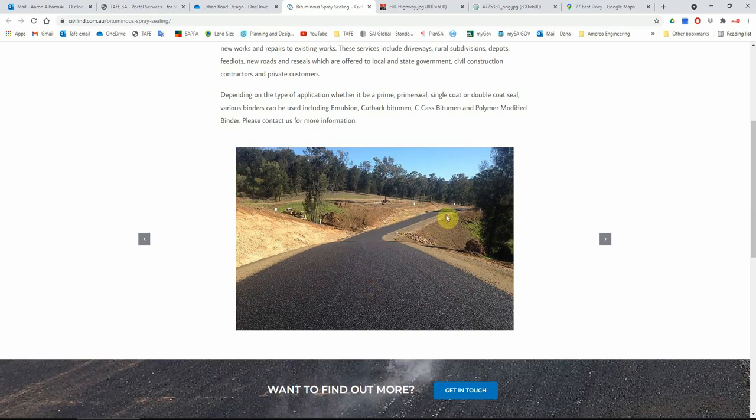These roads are designed to service two towns, for example, far away from each other. People usually need to drive a long distance, so they need to get there in a reasonable time. So the speed limit on those is high, and to provide that safe drive, we have to create as flat a road as possible. So we have to create a road with safety measures on it by creating the areas of cut and fill, so we can maintain the K values correctly, the horizontal radiuses, all of those that we discussed.